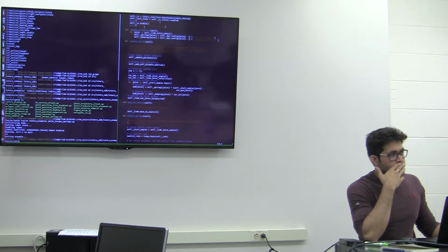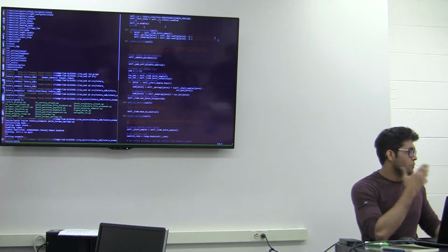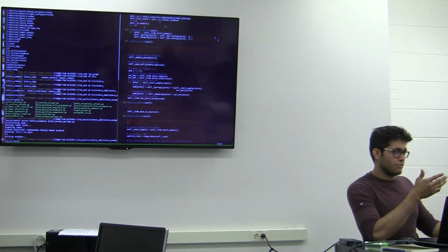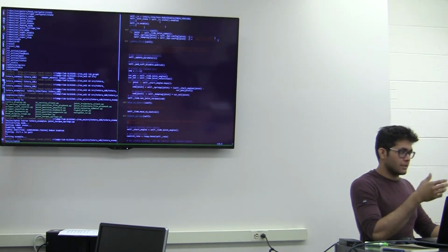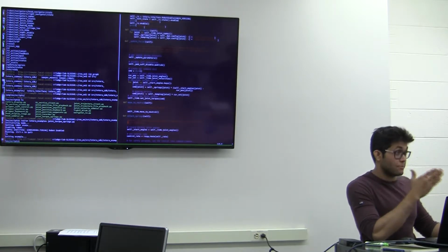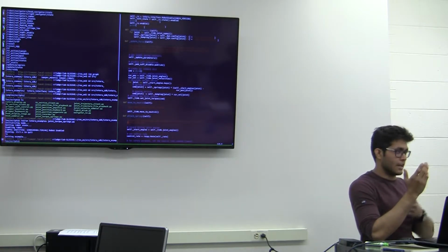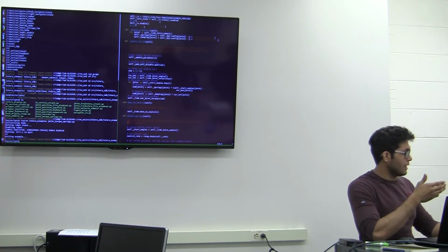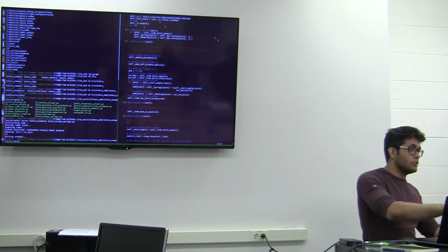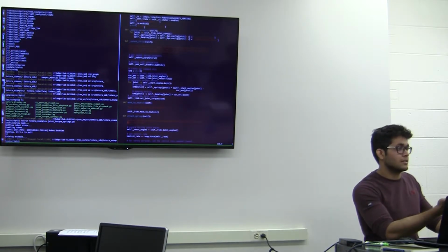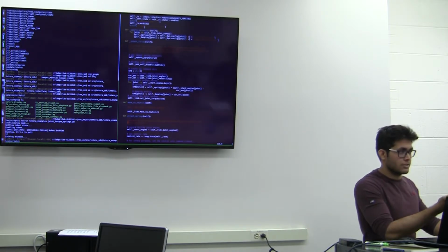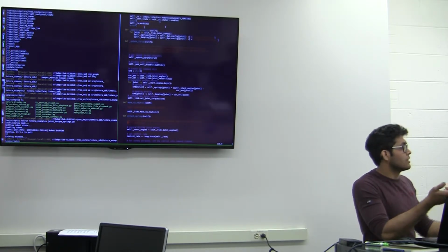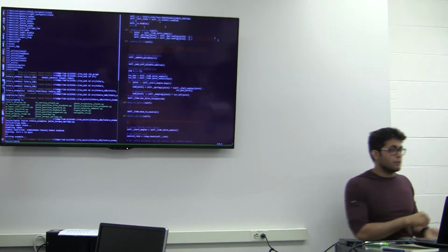Suppose I wanted to pick up an object, what is the general procedure on the board? Again, if it's not hard-coded and you want to do image processing, then you usually have a tag or something. Your camera will use that tag to detect the position. Now it knows the position in world coordinates or camera frame coordinates, and it moves to that position. You have to give the command. You can give the command for positions in world coordinates, or in joint coordinates, so angles also. If you give the commands in world coordinate positions, it will move to that place.